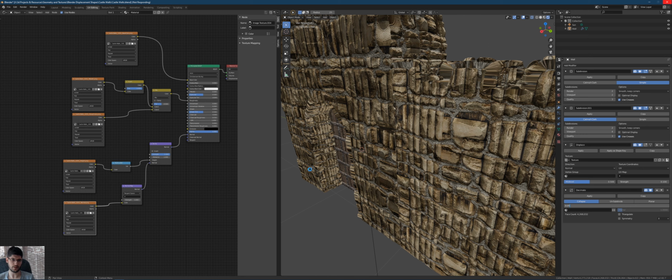And as I've said, if you guys know of any other way to fix displacement maps on the edges, please let me know. But that is the only way that I know of, at least so far. I'm sure in the near future they're going to find better and better ways to fix this. And also, I hope that the guys at Substance Painter will have their meshes be able to be exported with the original UV maps rather than having all of them overlap. Because if I would have exported that mesh from Substance Painter with the default geometry and everything that we did, which by the way would actually be a more suitable mesh for us to be used.